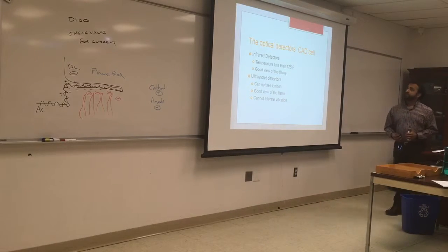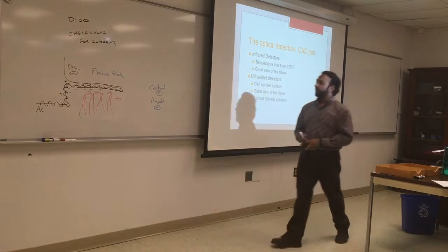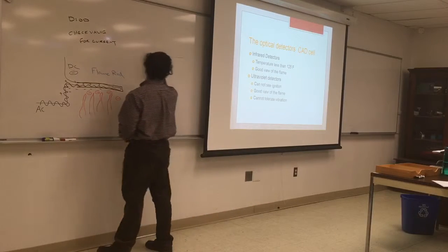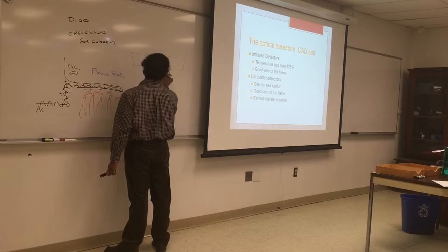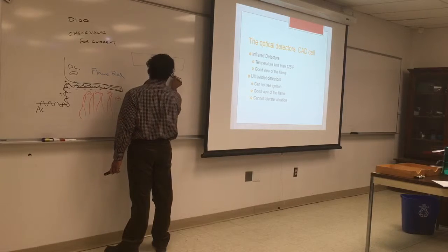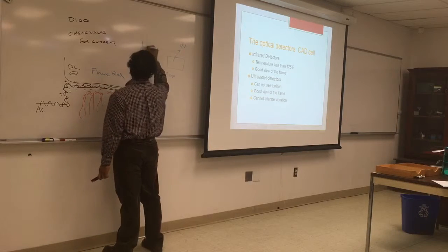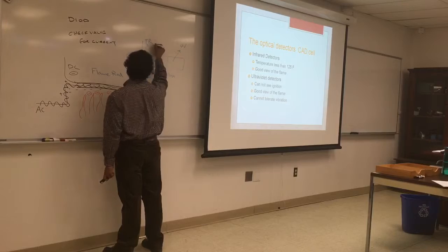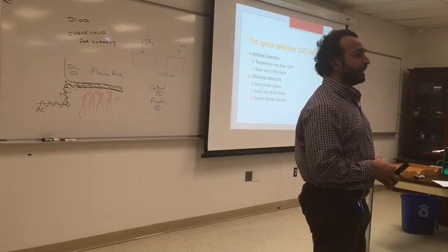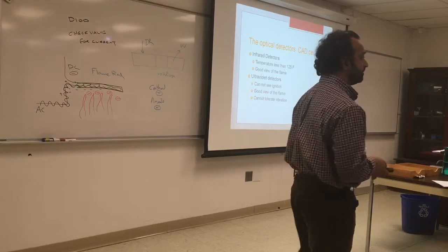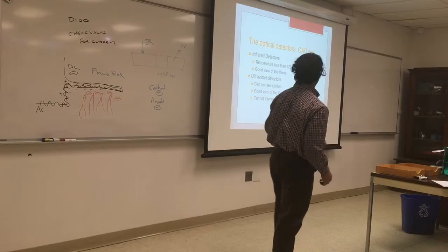The other ones we have are optical detectors, where they will see the light. And again, we said light comes with different spectrums. We have visible light, we have ultraviolet, and here we have infrared. So this is all light. These are all waves. We can detect those waves coming from the flame. Doing that, we can know how much flame is in there.